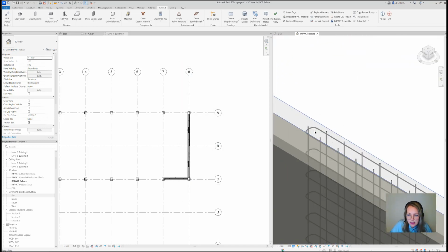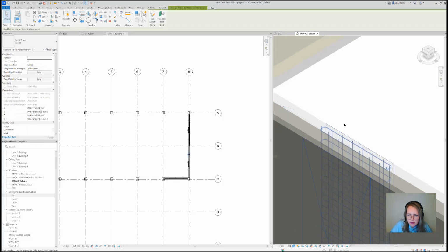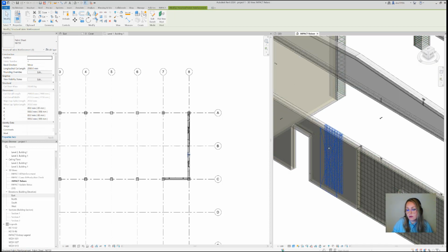I have a bended mesh made out of a rebar. It's the N shape code. So if you go and try it, I want to say that you need to activate the shape codes that you're going to use for this command. It's a little bit technical, but in the Impact Standard Admin tool, you need to add the shape codes that you need in a variable. Everything is documented in our Impact wiki, so if you intend to use this draw bended mesh functionality, it's quite easy.